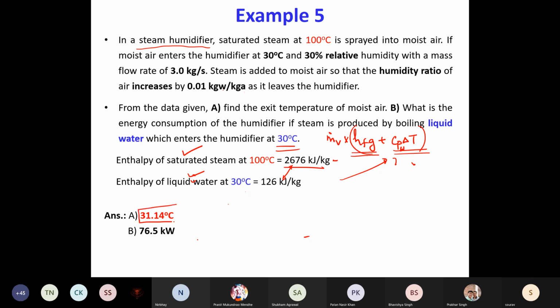You see in the answer, there is only a very small amount of sensible heating and a very large amount of moisture rise. So 10 grams per kg of dry air, which is quite significant actually. So your process line, if this is state 1, the state 2 temperature is almost 30 only, so only 1 degree rise. So the process is like this. When you use a steam humidifier and mix this steam into the incoming air, the process that you follow is definitely heating plus humidification, but the sensible component is quite small.